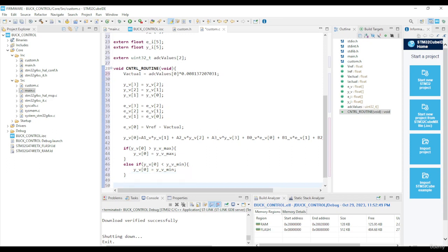And the next stage, of course, you want to update the duty cycle. CCR1 states that if we're getting CCR1, you want to equate that to, and this is where the type casting comes in, int, and here you have to state max duty. Now this max duty varies from controller to controller, but you have to state max duty explicitly.